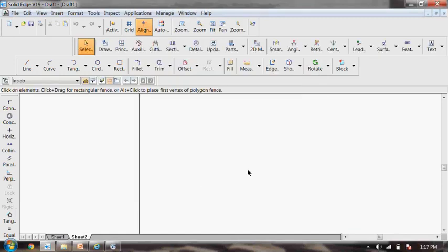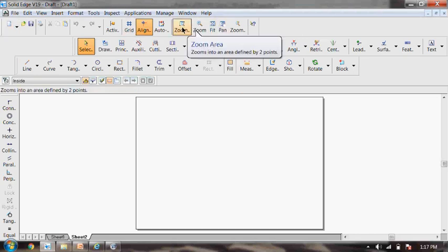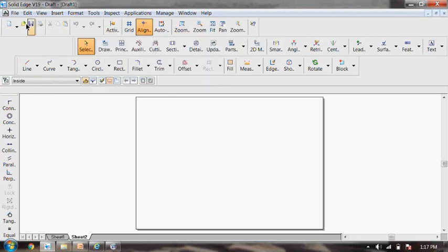and then click on width. We'll click on fit screen. So these are the three types of bars which should be available. Before the lockdown of the class, I had explained all this to you. This is the main bar, this is the drawing view bar, and this is the drawing bar. These three types of bars. In the main bar, you find the fit command, zoom command, and then copy, paste, cut, print, save, open, new. All this you find in the main bar.